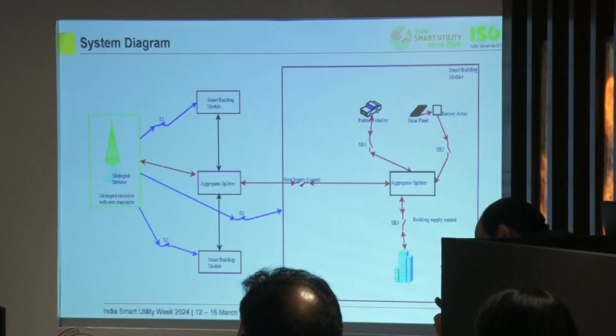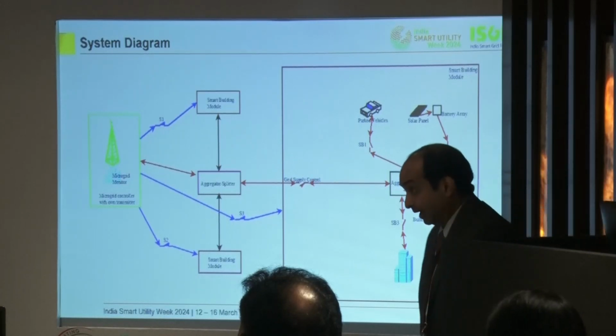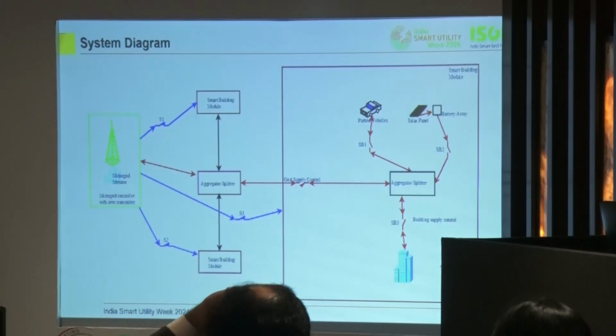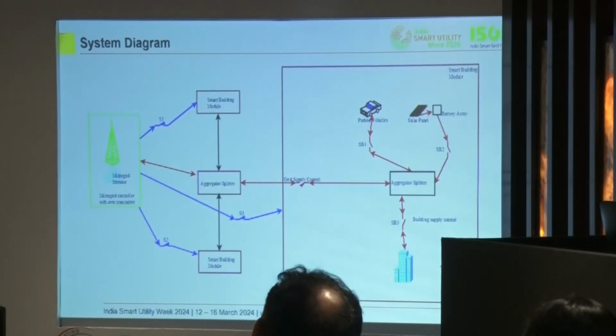In your buildings, you have the essential buildings. Each building has one master controller that controls the whole building. Each of the units, dwelling units or industrial units, whatever you call them, has its own IoT modules that read data, take measurements based on the sensors, and provide them to the lower-level master building controller. I call it BCS. This BCS communicates with the top-level microgrid controller. The top-level microgrid controller knows the state of each building and the state of the aggregate, and whether it can be used to augment the grid supply. It depends on the protocol they have defined. It is not a hard protocol, it is a soft protocol. You can define your own protocol, but this is what I am proposing at the simplest level.